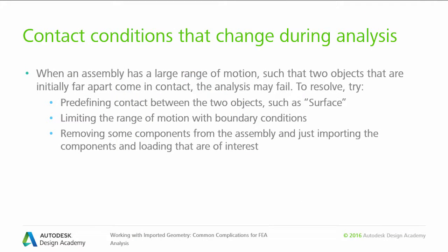Finally, another complication you may encounter in FEA work is when the distorted shape of a structure under load causes the contact conditions to change. To handle this condition, do one of the following. Define surface contact between parts so that they are free to come into contact, slide, or separate relative to each other. Additionally, a nonlinear analysis type can be used to support rigid body motion and large displacements.